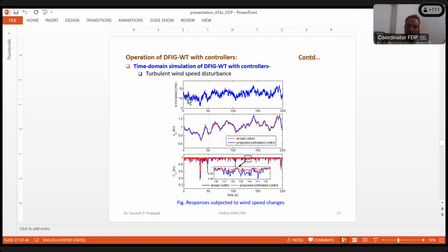So every time there is a change in wind speed, the turbine power coefficient will have some spike, because as soon as the wind speed changes, the turbine will not change its speed immediately, because it has its own inertia. So it takes time to get near the optimal value. That's why these spikes are there. If we imagine that the turbine or generator does not have inertia, then CP would always remain constant, or always remain one. But since they have inertia, it takes time to reach the maximum power point again. So that's why there is a change in the value of the turbine power coefficient CP in the last curve here.